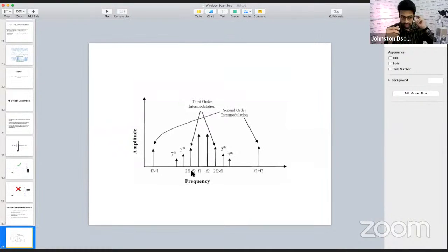Okay, that's the reason why digital systems are preferred, because you don't need to do compression and decompression in digital. All the audio is taken, converted by an A to D converter to digital first, and then it sends a very light digital data to the receiver. And there is no compression and decompression. That's the reason why digital audio over wireless is cleaner than analog audio over wireless.